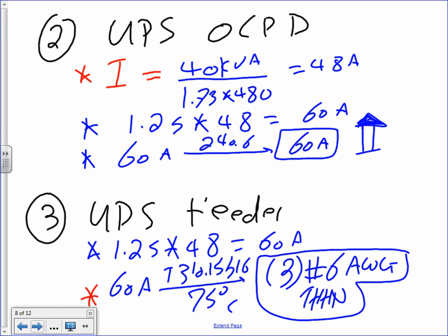Now, what I'm hoping is you guys will be the ones who write these standards or modify or adjust them. So when you go to your company, Jeff, if they say, who's the idiot who told you to use number 6? Ouch. I hear you. Because we're using number 2, no problem. We're doing a minimum. A lot of people go much more than a minimum because of voltage drop and all this stuff. They up it one size just for voltage drop. Okay, so we got that one. Any questions about the minimum size?